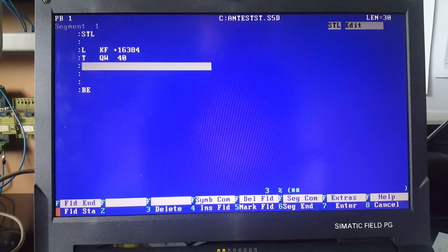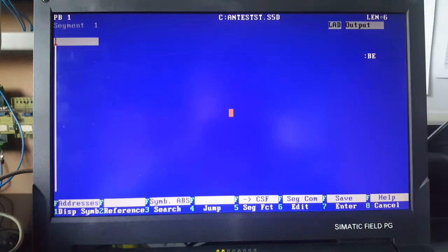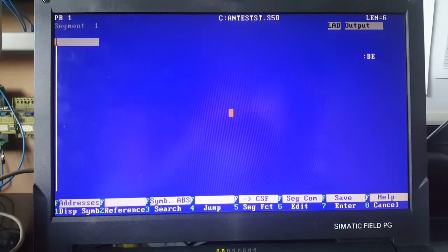Siemens S5 offered the user 2 ways of getting these signals in and out of the PLC. The first was by directly writing or reading from the analog output/input. The second way is by using the scale/unscale function blocks FB250 for scaling and FB251 to unscale the analog signals. In this video we will look at the scale/unscale blocks and how to parameterize them.